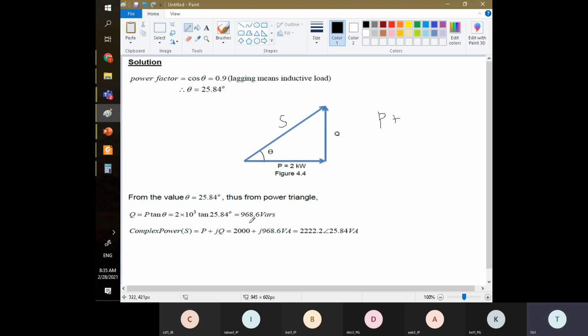And then this one we found to be positive, 3 plus j, and this number is the reactive power, VAR. Voltage current reactive. So this number here is called the Q. And we can also convert this to the phasor form. This is the rectangular form.